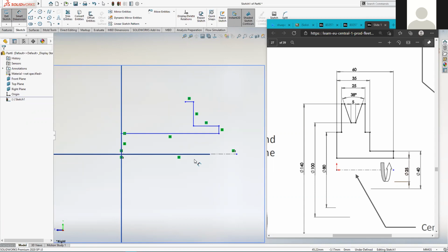We get to practice our diameter dimensions again, because we did cover this the other week, but it can take a few attempts to get it embedded as knowledge. So yeah, we want to create diameter dimensions. We don't want to dimension the radius. All rotational parts like this tend to be dimensioned with respect to the diameters. You tend not to get radius dimensions on parts such as this.